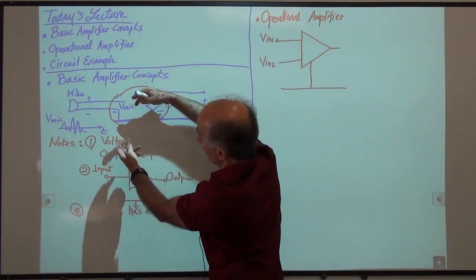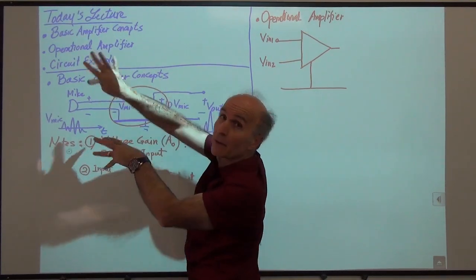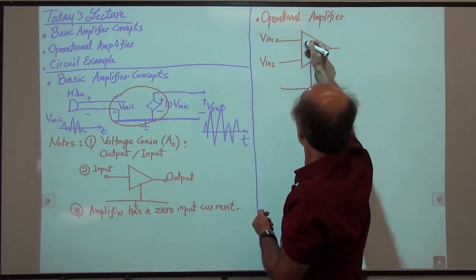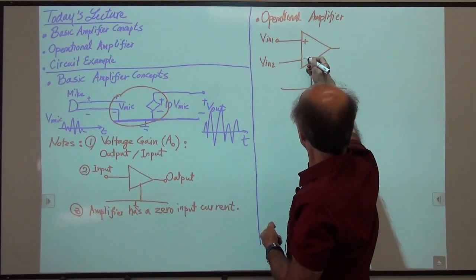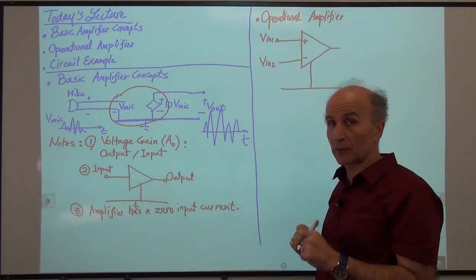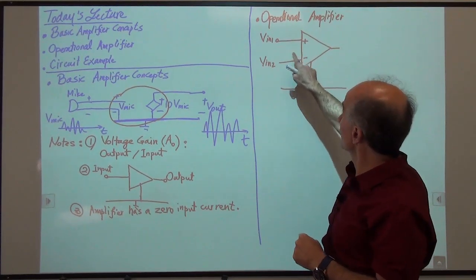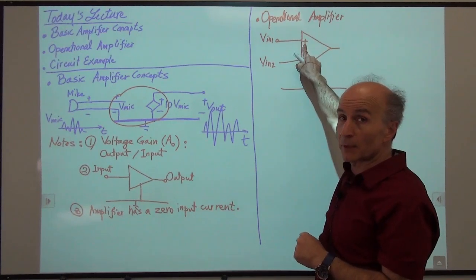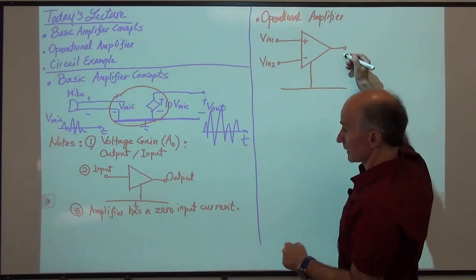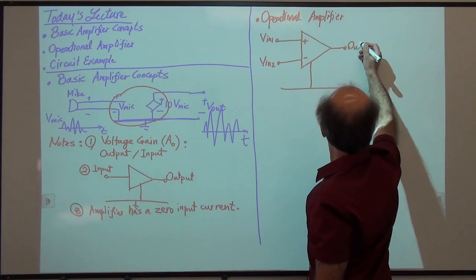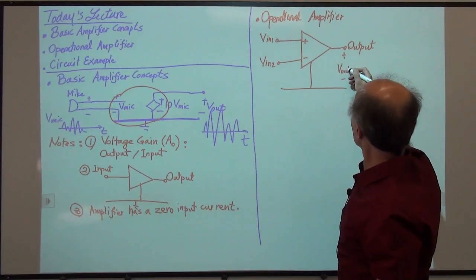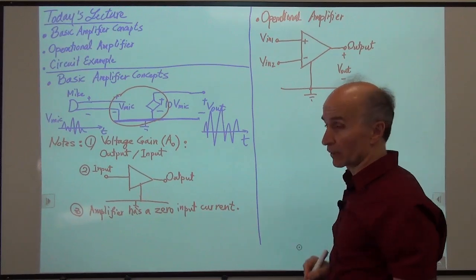So here, remember, there was a voltage from this microphone to ground. Imagine that there's another microphone, and that has another voltage with respect to ground, and that's going, for example, here. And then we place a positive and a negative sign here. These do play a critical role in what the circuit will do. So we have to remember that there's a positive here, there's a negative here. One input goes to this positive input, one input goes to this negative input. And the output is still here, just like the simple case. So this is the output, and what it really means is that there is a voltage between these 2 points, V out, right? And of course, this is our common ground.